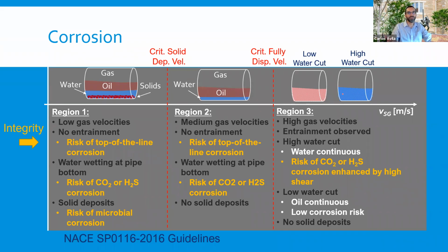And then you can have either the water dispersing the oil, which would help you, because you're isolating the water as droplets, and then the oil will be touching the pipe instead of the water. That's directionally correct. You want to do that. But depending on the water cut, that may not happen. If you have high water cut, then what you're going to get is the oil dispersing the water. So anyway, I'm not gonna go through all the words in this slide, but I just wanted to get you